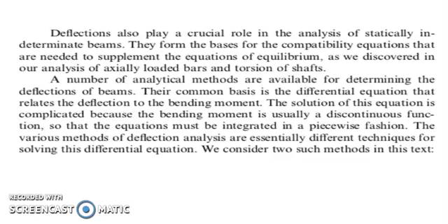A number of analytical methods are available for determining the deflection of beams. The common basis is the differential equation that relates the deflection to the bending moment. The solution of this equation is complicated because the bending moment is usually a discontinuous function, so the equations must be integrated in a piecewise fashion. There are various methods for deflection analysis, which differ in the techniques for solving this differential equation.